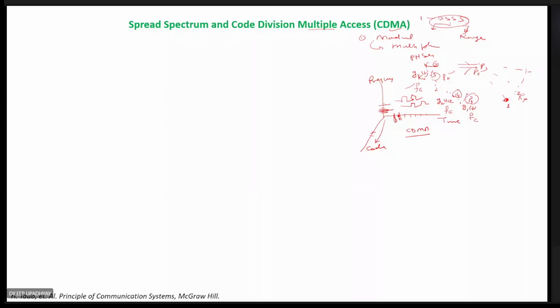At the same time, the second drawback of considering this assumption is that CDMA suffers from the near-far problem. What is the near-far problem? This near-far problem appears since we have assumed that our transmitters transmit equal power. It does not happen in cellular communications.